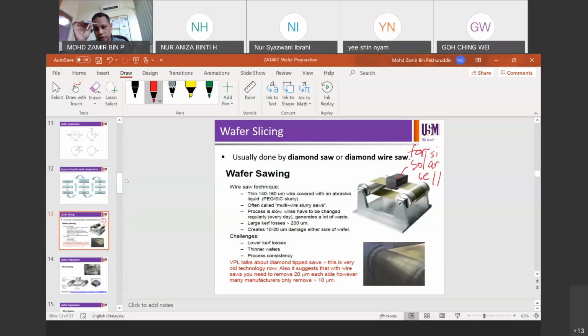Yes, higher surface area, good. If you look at a solar panel, we want all the area to have solar cells, right? We don't want to use round. If you use round shape, then you put the next round shape, you'll see the openings, a lot of open areas. So if you use square shape, you can close the whole surface with solar cells, and then you can harvest more current, or higher current. Okay, that's why in solar cells we want to use square shape. Okay, higher surface area.